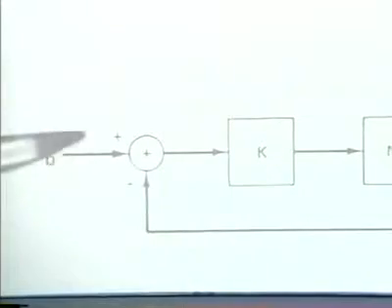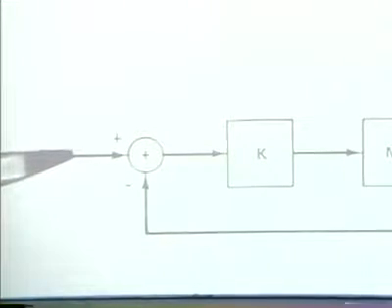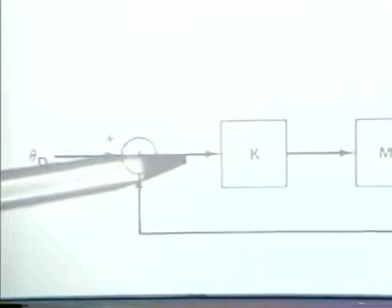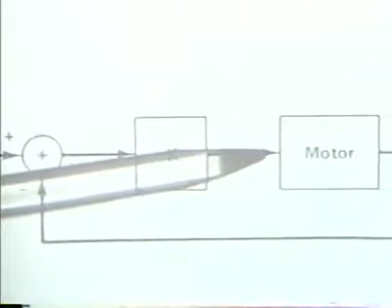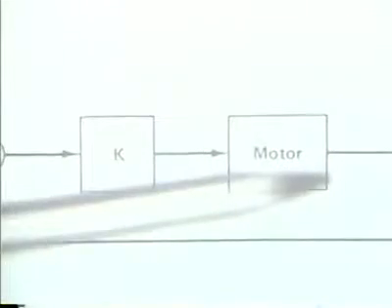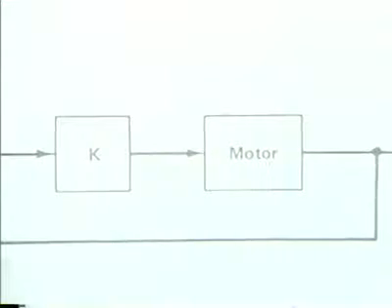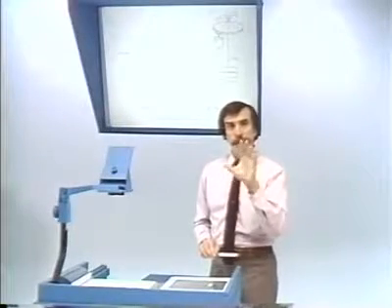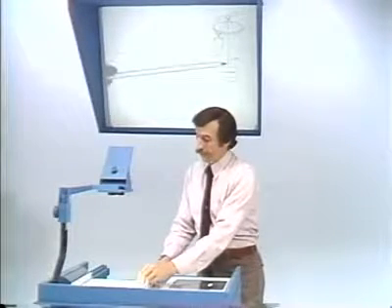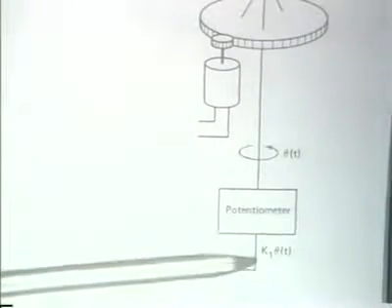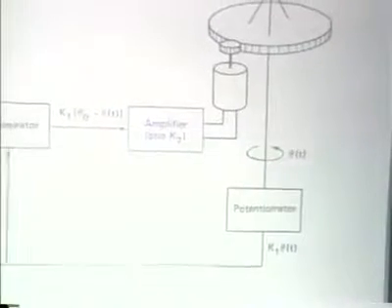And the difference between those, which essentially is the error between the platform positioning and the desired position, would be put perhaps through an appropriate gain or attenuation and used as the excitation to the motor. So in the mechanical or physical system, that would correspond to measuring the angle, let's say with a potentiometer. So here we're measuring the angle, and we have an output which is proportional to that measured angle. And then we would use feedback